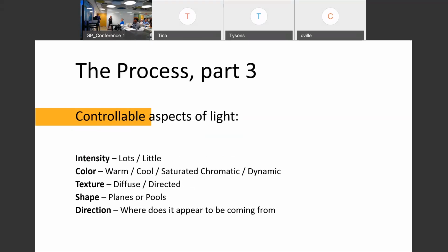But there's different ways of approaching it to still meet all 5 of the corresponding elements. Controllable aspects, the simple way we understand it is, all right, we need a dimmer. Nobody wants to go to the wall and dim things anymore. Let's get the occupancy sensor. Let's get the daylight sensors. You know what I mean? So the first row off the windows, it's great. And now you're saving more energy as well without anybody having to do anything. So it really works that way.